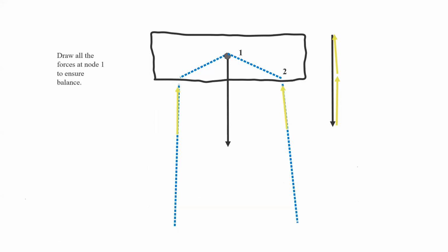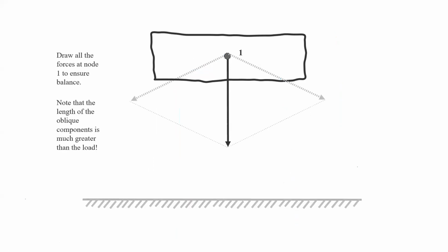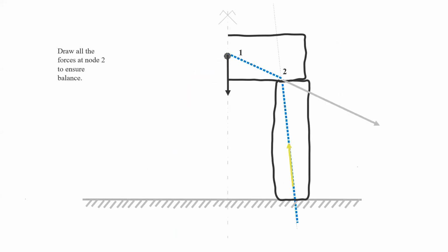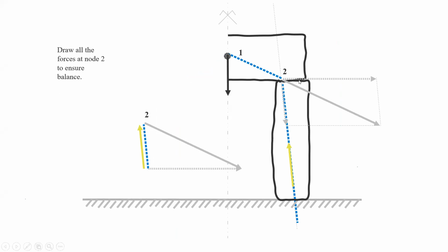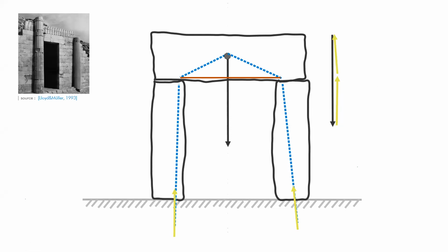About decomposing the equilibrium, you can see that just resting on the analysis with the first term and getting the equilibrium above, you are able to decompose very quickly to this. The resulting is that the force you get here on both sides have to be equilibrated to another direction here, and you won't be able without adding a horizontal component onto it. And you can assess what's the value using, again, a triangle of forces, and it will demonstrate that since you're not able to push here toward the node, you will need an internal force that will be appearing in the system. So demonstrating what's happening in the system. And indeed, you have the traction force that could lead to a break into an arch as here.